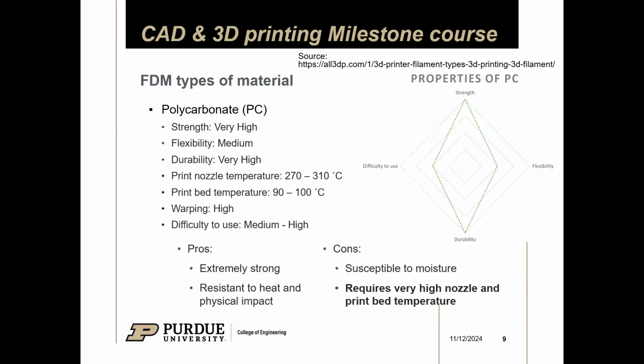So I'm going to be reprinting some parts of this printer in a carbon fiber PET, which is pretty cool. But it'll make the gantry more rigid, and then I can go faster. And I always want this printer to go faster, but you'll see in a moment. But yeah, polycarbonate's pretty cool, but it's pretty hard to print. So unfortunately for us consumers, it's pretty hard to make or print something out of pure polycarbonate unless you have an insane setup. So even a printer like this might have a hard time printing polycarbonate, unfortunately.